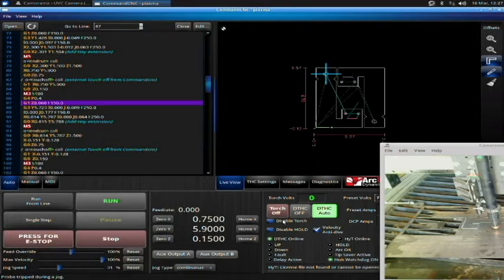Now, a common error code is a 030 error, and that's called a stuck consumables error. That's probably the most common error you'll see when you have a misfire. That can simply be something in the tip of the torch didn't quite work exactly the way the plasma wanted it when it fired, and so it gave an error. So it wasn't able to strike the arc. A lot of times that's not an unusual problem, and a lot of times you can just simply do this process, rerun the code, and the machine will fire the second time. Okay?